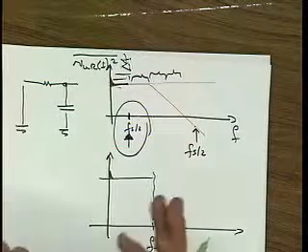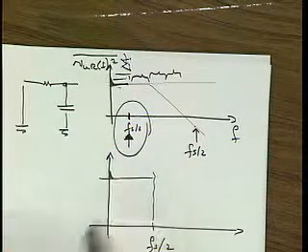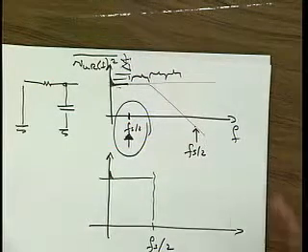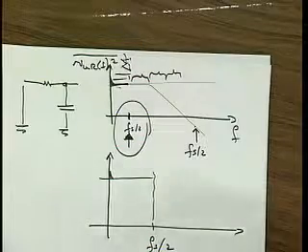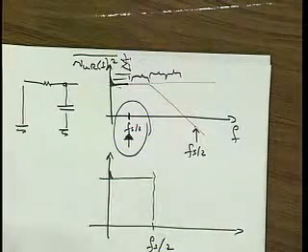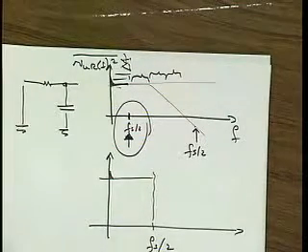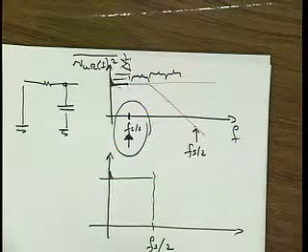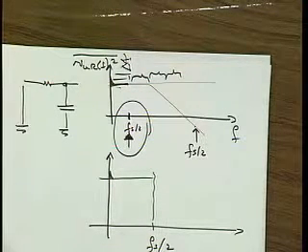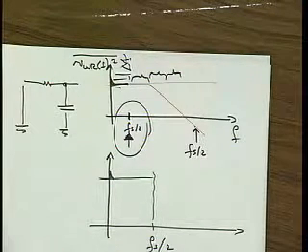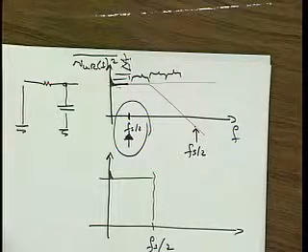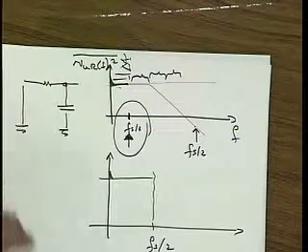So narrowband effects, such as 1 over F noise, or the signal for that matter, which ultimately is going to be in the picture, better not alias, right? Sure. But as far as the broadband white noise is concerned, under reasonable circumstances, generally it is white.